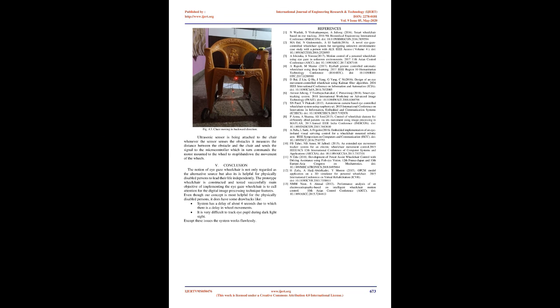Ultrasonic sensor is being attached to the chair. Whenever the sensor senses the obstacles, it measures the distance between the obstacle and the chair and sends the signal to the microcontroller, which in turn commands the motor mounted to the wheel to stop or shut down the movement of the wheels. Conclusion. The notion of eye gaze wheelchair is not only regarded as the alternative source, but also it is